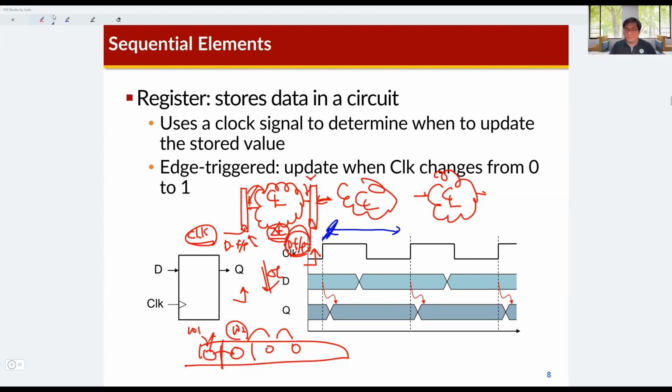Digital design works like pipelining, because it is composed of this sequential part, D flip-flops, and between two D flip-flops there is combinational logic. The output of combinational logic is sampled by the rising edge of the clock signals. Okay.